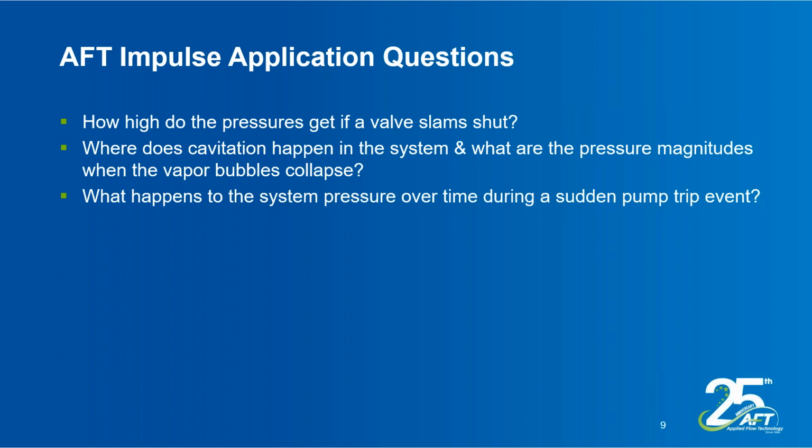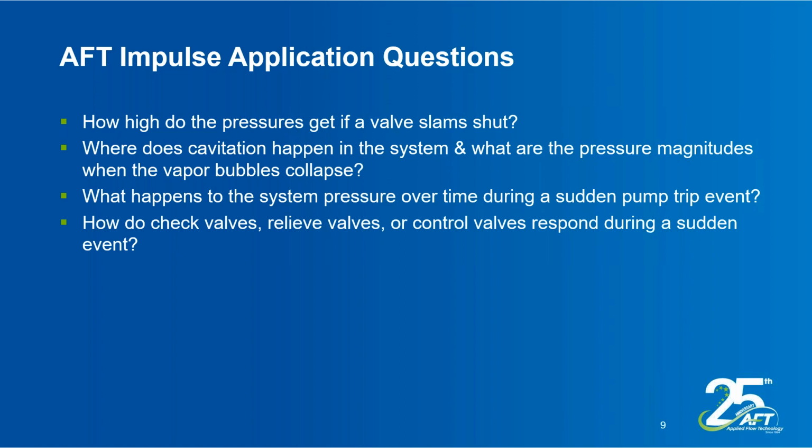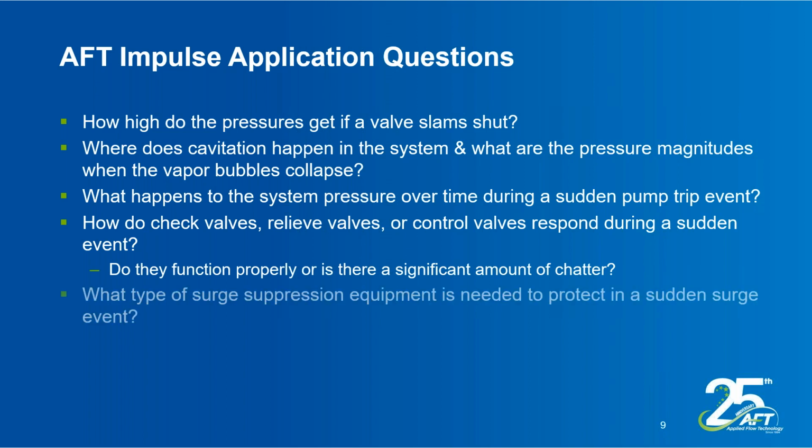Another application would be what happens to the system pressure if you have a sudden pump trip. So if you have a pump trip, your pressure will decrease, your flow will decrease. How does that affect what's going to go on in your system? How do check valves, relief valves, and other types of valves respond during a sudden event? So if you have a sudden valve closure, maybe you've got some check valves and relief valves that might start chattering or are just trying to relieve flow to different flow paths. That's what you would use Impulse for. Are they functioning properly, or again, are they chattering? You definitely don't want them to be chattering.